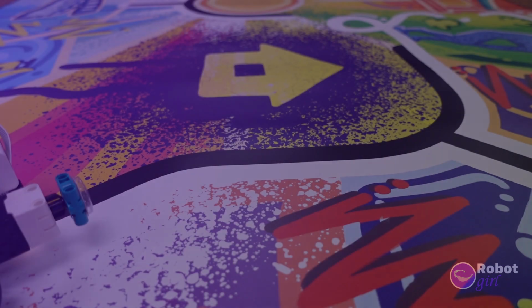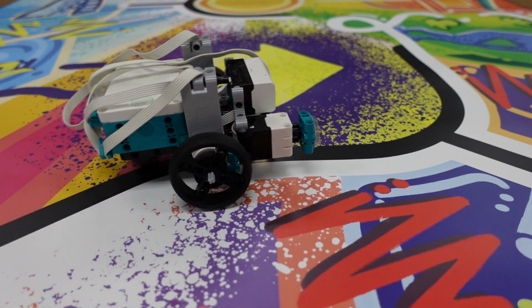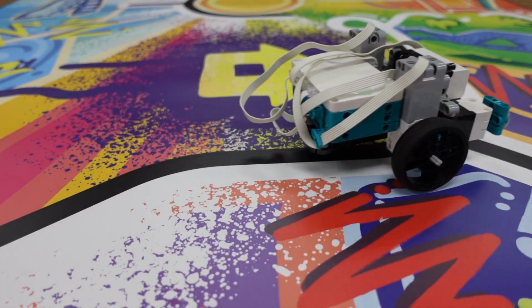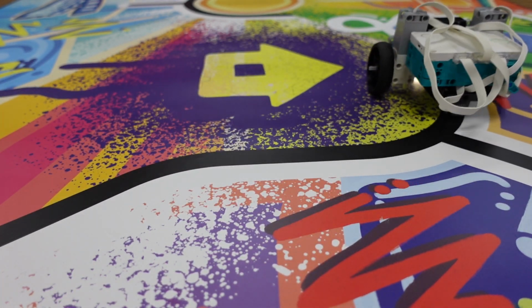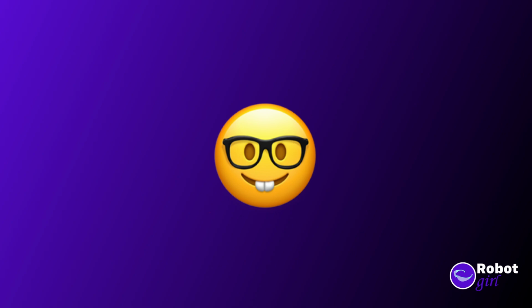If you've ever been in First LEGO League, the line followers that most kids learn to code use this kind of bang-bang control. You'll notice it because the robot always turns a fixed distance, so it ends up zigzagging back and forth over the line. But we can be more precise than that.